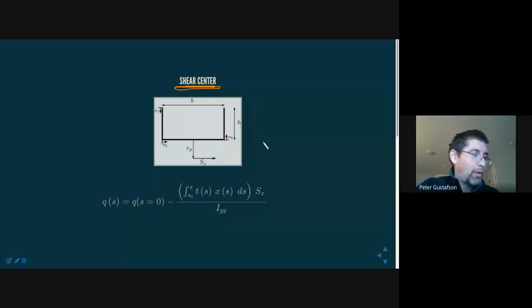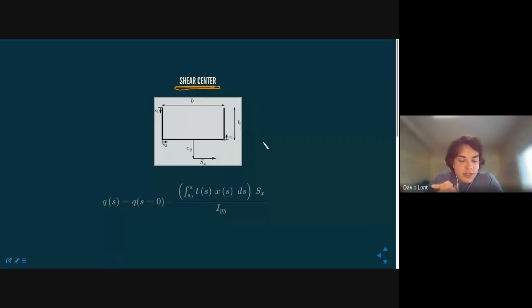So ask the question again. In what context did this discussion come up? This is in the class for aircraft stability and control, and there's this thin region denoted HN, the aerodynamic center, and then this HN prime. If you're between these two sections, and that's where your center of gravity was loaded, the plane is still technically statically stable, but to the pilot, the controls feel reversed, or so Dr. Rose said.